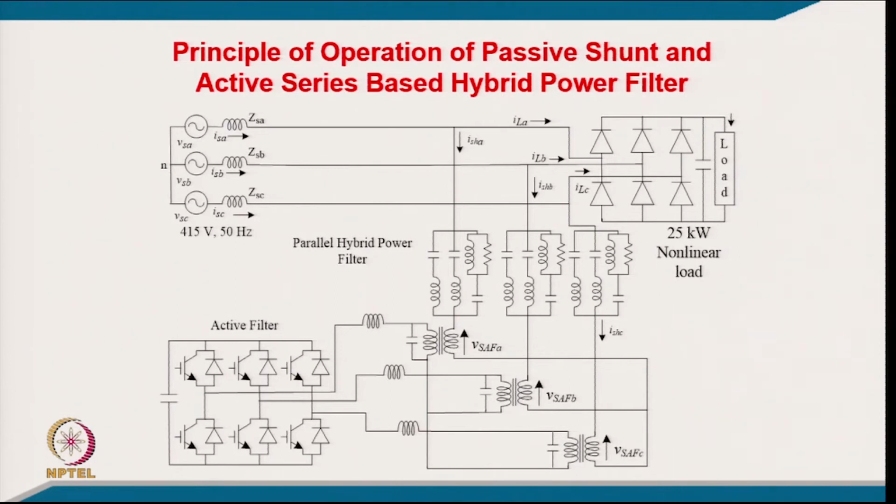And this is typically quite a popular topology. In this case, it is a kind of voltage fed non-linear load, but a major amount goes to the passive filter. We connect in series with this a small rating, 3 to 4%, series active filter, so that this avoids the resonance, and the other is it makes the variable harmonic compensation. So, you can inject an adjustable harmonic voltage in such a manner that this sucks the harmonic current, the entire harmonic current of the load, and becomes quite effective.